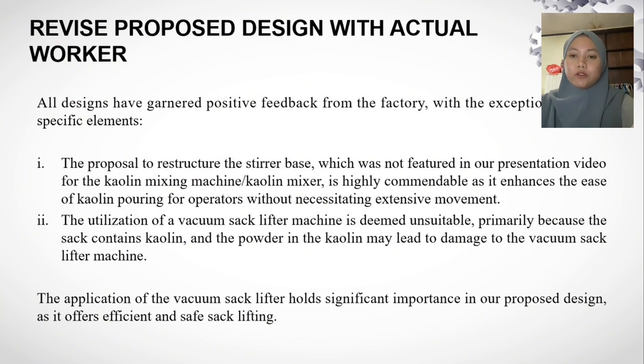Second, the utilization of a vacuum sack lifter machine is deemed unsuitable, primarily because the sack contains kaolin, and the powder in the kaolin may damage the vacuum sack lifter machines. But the application of the vacuum sack lifter holds significant importance in our proposed design. It offers efficient and safe sack lifting.